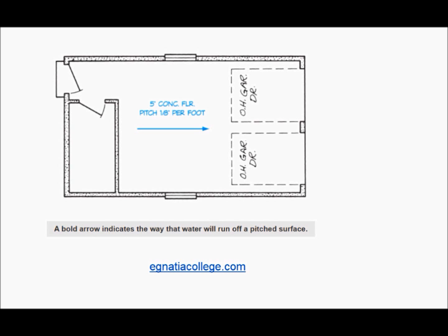All underground utility systems must be coordinated prior to starting installation, especially in commercial and industrial buildings. The service entrance section may have up to 6 sub-distribution sections or panels located throughout the building. Electrical feeders are required from the electrical service entrance section to these sub-distribution sections or panels.